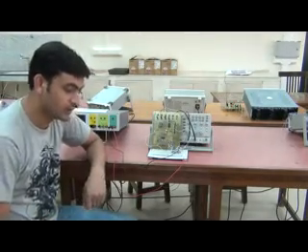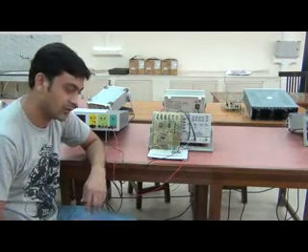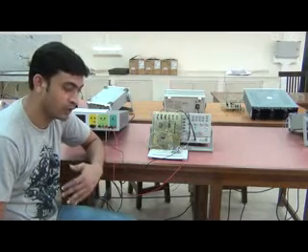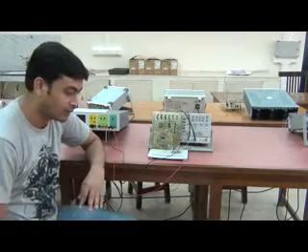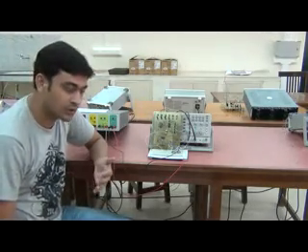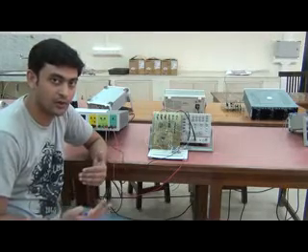In this, the clock for the second flip-flop will be the inverted or the complement output of the previous flip-flop for this ripple up counter. Since this is a divide by 8 ripple up counter, it will count from 0 to 7. It will increment by 1 from 0 to 7.